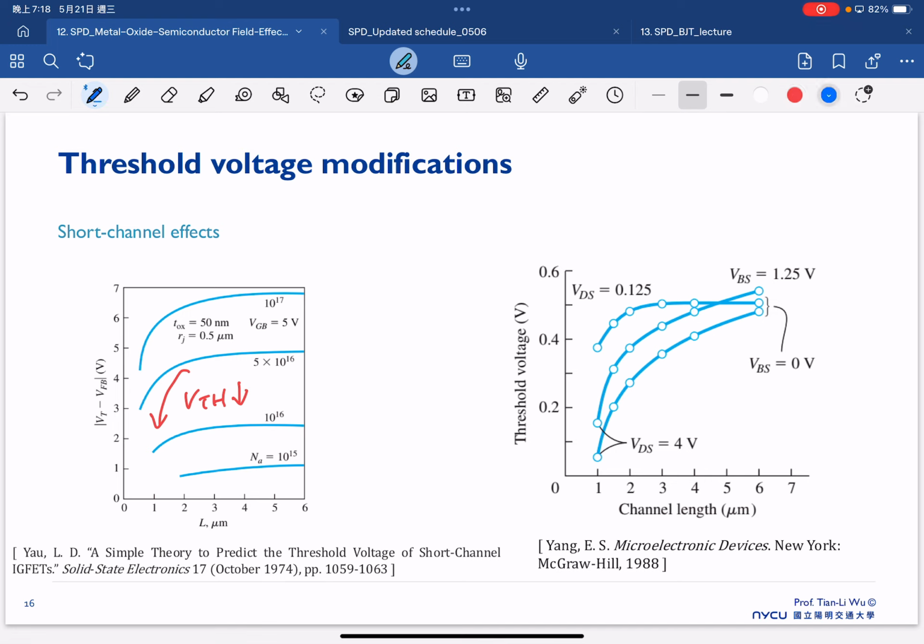And then the threshold voltage decrease suggests that this is a short channel effect. So this is the issue. Basically, we can see it in every kind of semiconductor device. So we have channel length decrease or VTH decrease, and sometimes we call this a threshold voltage roll-off. In the literature, you will find that some people call it that as well. And as I say, this is mainly due to the PN junction, no matter from source to substrate or drain to substrate.